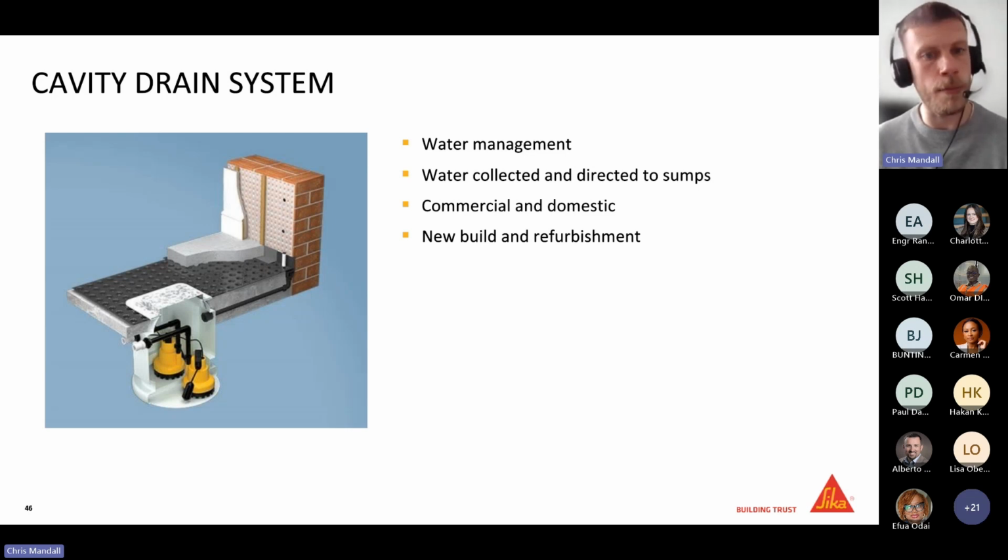So although it is incredibly robust and durable, where space is an issue, it may not be the most appropriate solution. Again, with the membrane on the walls, you've got an 8mm membrane on the walls that can't be left exposed. You'll typically have plasterboard in front of it or a cavity wall. So you're losing space on the perimeter of your basement to incorporate that channel as well. So it's a very robust system, very durable. It works perfectly fine on a lot of projects, but there are still some certain projects where it may not be suitable and another system may be more beneficial.